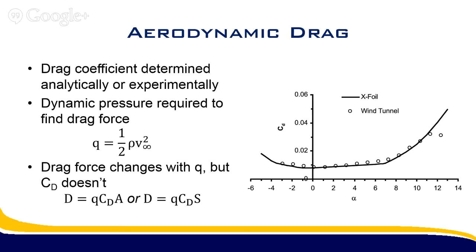But obviously Mother Nature doesn't discriminate, so the drag coefficients are actually based on which reference area you're using, and it varies from place to place. Usually we'll end up using that cross-section area, the A, but in aircraft you'll usually use the planform area, S.